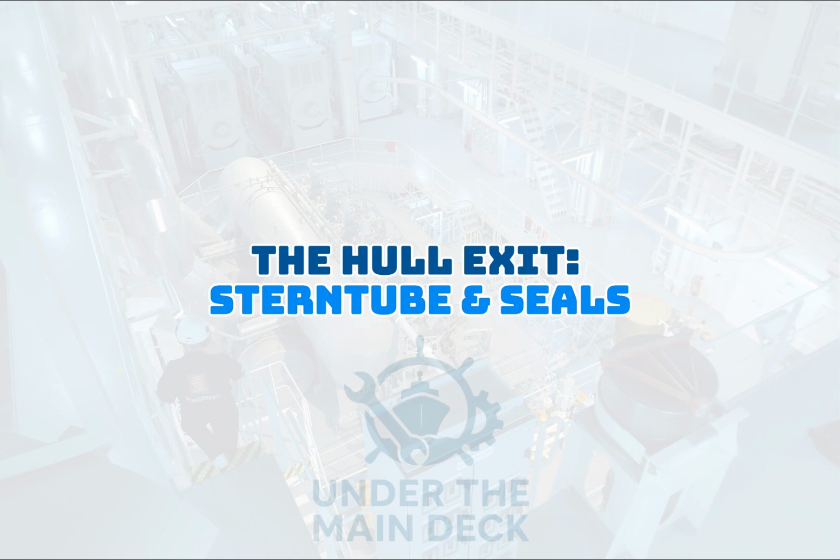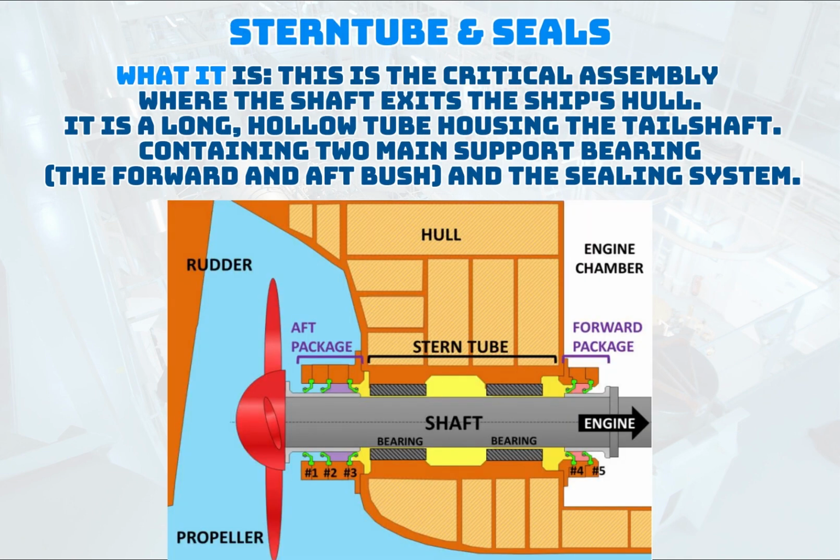The hull exit, stern tube and seals. What it is: this is the critical assembly where the shaft exits the ship's hull. It is a long, hollow tube housing the tail shaft, containing two main support bearings, the forward and aft bush, and the sealing system.